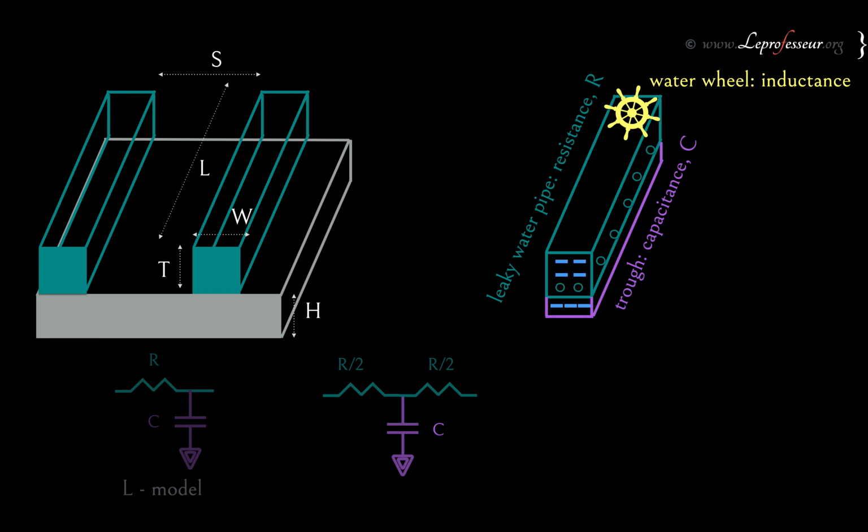Then the second one is where you see the difference. In the first one is a very simple resistance and capacitance, with the capacitance at one end of the resistance. Then the T model, where you have the capacitor in the middle and the resistance is half on each side of the capacitor. And then one more kind of model where you have half the capacitance on each side of the resistance, which is called the pi model.